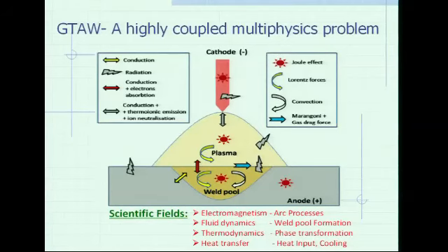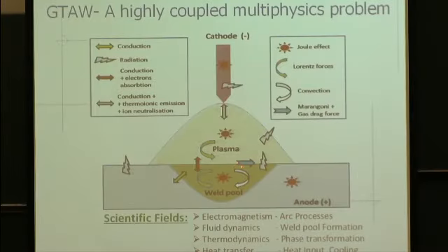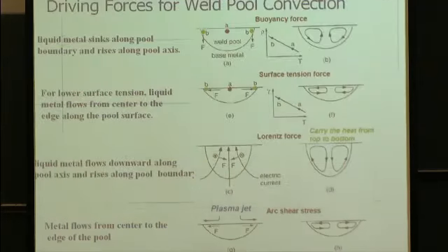And we have also the Marangoni force. This force acts on the top surface of the weld pool, and it is quite important because it will push the fluid from the center towards the border of the weld pool. So we have some motion. If I go a bit into the detail of these forces in the weld pool,